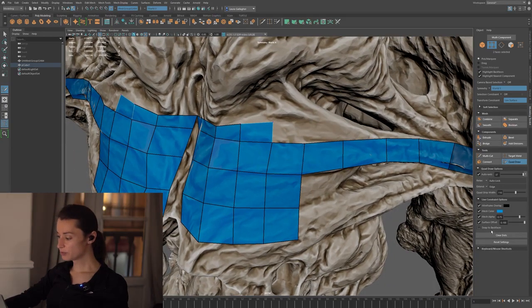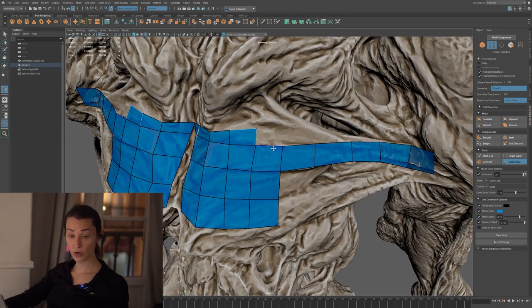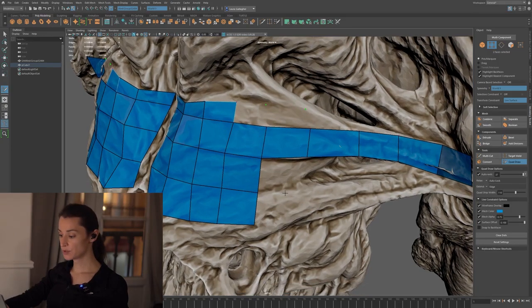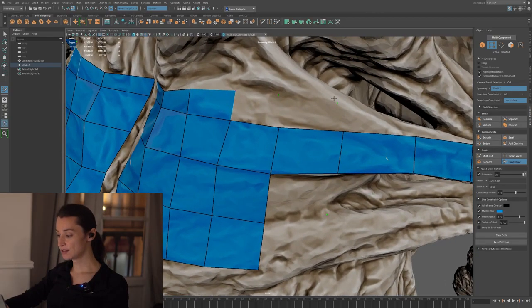And that's mostly it in terms of basic options for Quad Draw. One thing we haven't talked about is what happens if you simply click on a mesh. As you can see, if I just click somewhere over the mesh while I'm in Quad Draw mode, I'm actually placing individual vertices, which are not actually connected to anything yet. So these vertices are just floating in space.